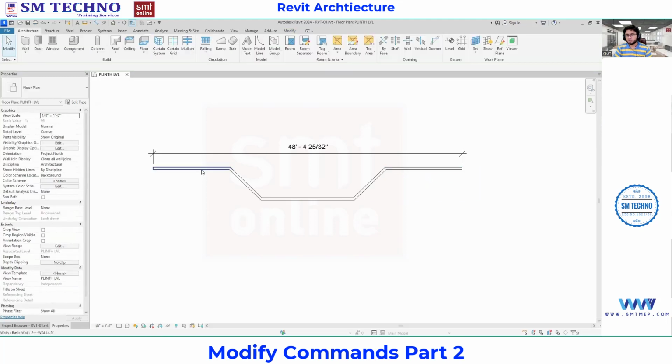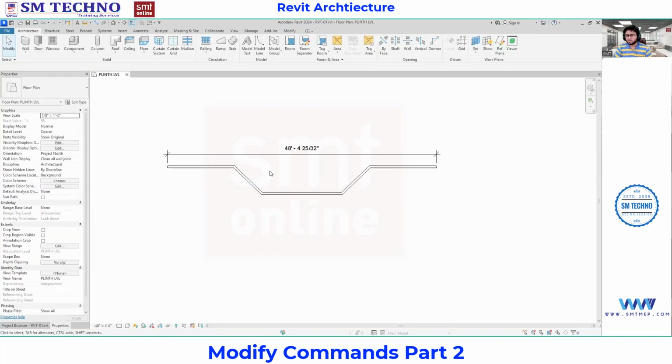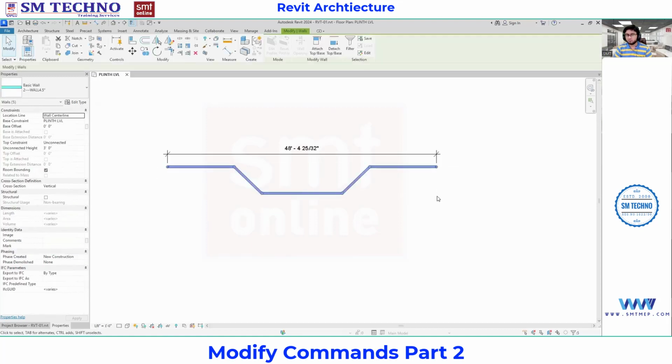If you want to modify, you can change from there. Like 12 feet is a value here. If you want to increase, you can increase. But anyhow, right now we are going in a rough way. So I'm selecting this wall. After selecting this wall, I'll be going with the Modify Element tab.